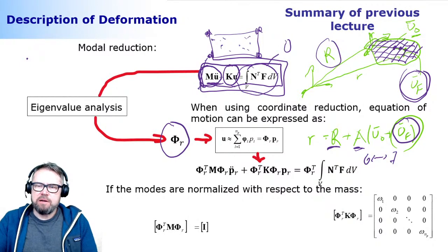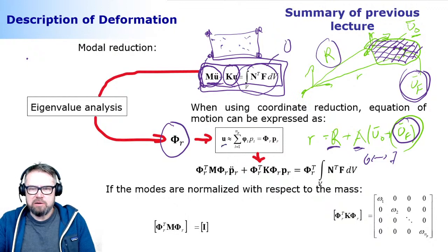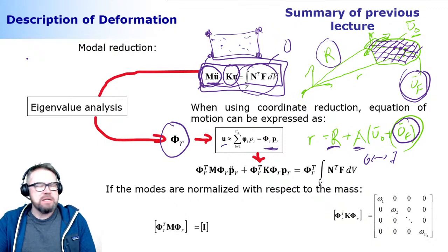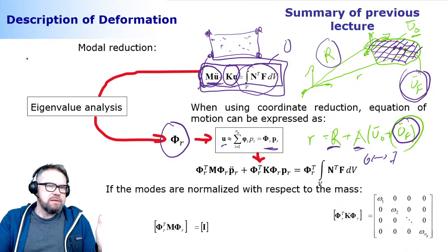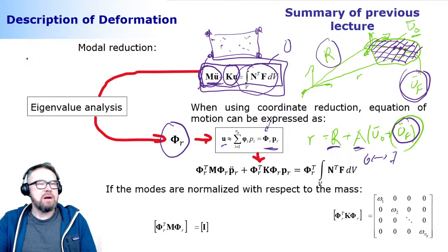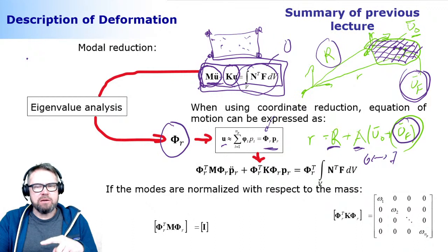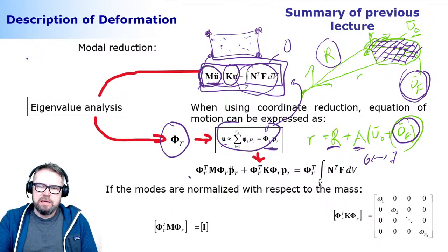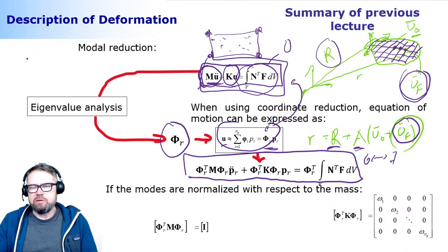And we have this very important relation between the nodal coordinates and modal coordinates, and is related based on this deformation matrix here, which comes from the eigenvalue analysis. Now, what happens when I'm moving from nodal to modal coordinates is this. When I do this substitution, it is substituted into my original equation here. The original equation can be written like it is shown here.